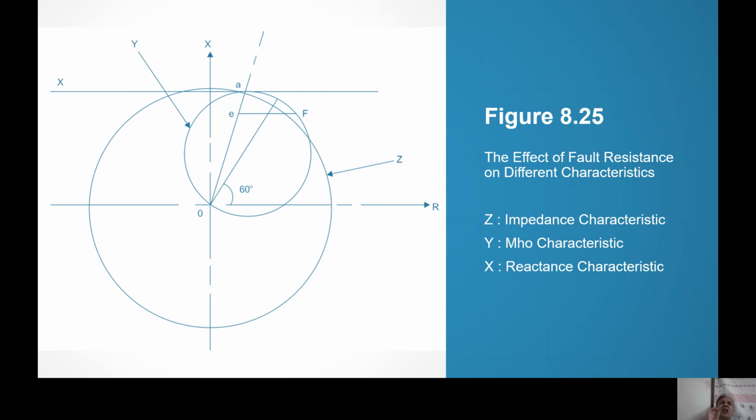If you have got 20 kilometer, say, I was telling of Ukai hydro to Ukai thermal, a 6 kilometer long line, 220 kV. So the impedance of a 6 kilometer line would be maybe 1 ohm or even a fraction of an ohm. And if an earth fault occurs, the earth fault resistance is 20 ohm, because an earth fault is flashover, tower, soil resistivity.